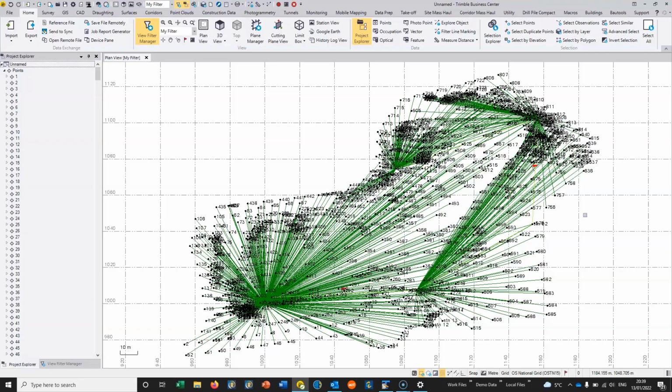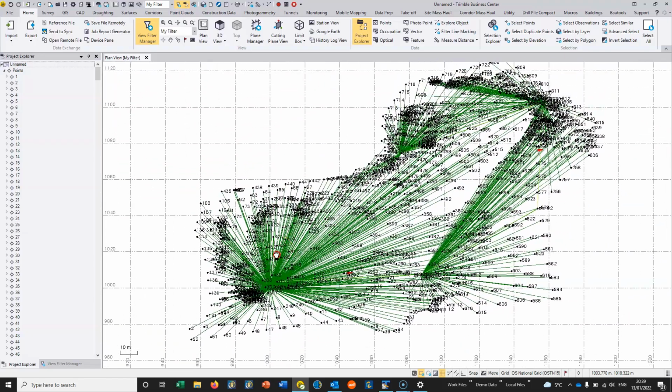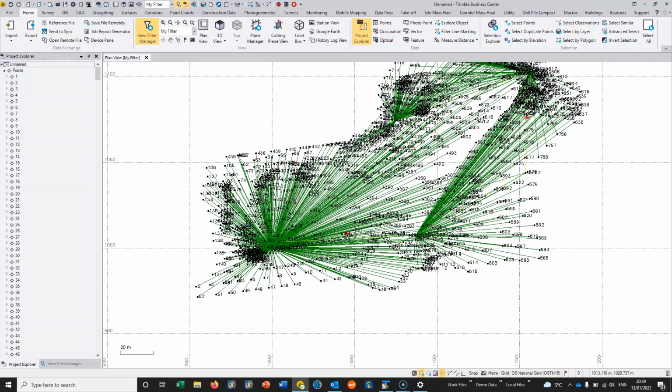Now, often the easiest way, which is what the surveyor did in this case, is to actually survey the stations from the setup, and ideally from an individual setup, with the total station for which coordinates will be later available. So in this survey, the surveyor has measured 2 nails.